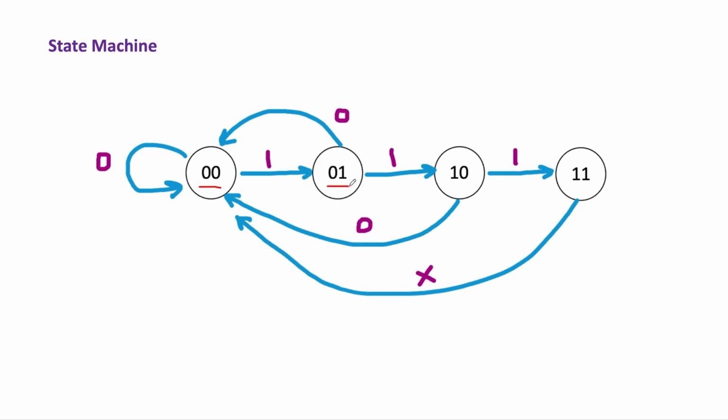On the same ground, you check for begin again and then move ahead to the various requests in a round robin fashion. Request 1, 2, 3 and 4. For the fourth request, I have a don't care because whether the begin signal is 0 or 1, in both cases you move back to request 0. So this was our state diagram, and further we'll be looking at the Verilog code for this process.